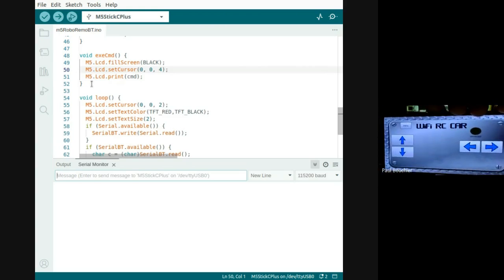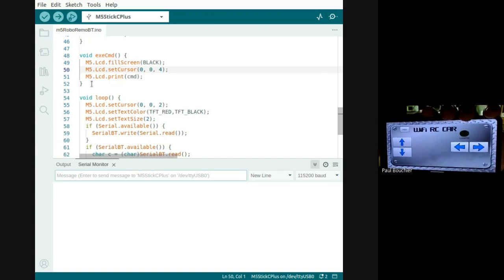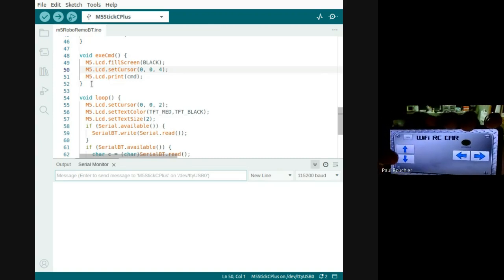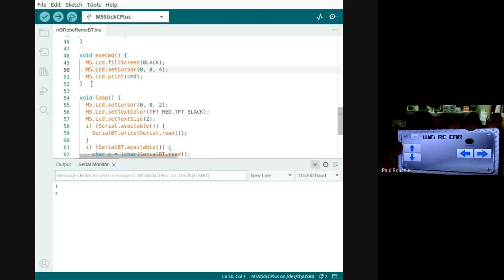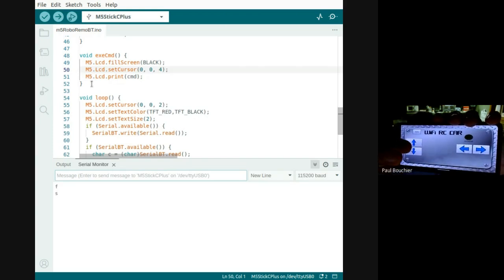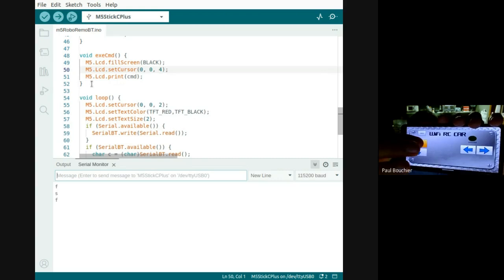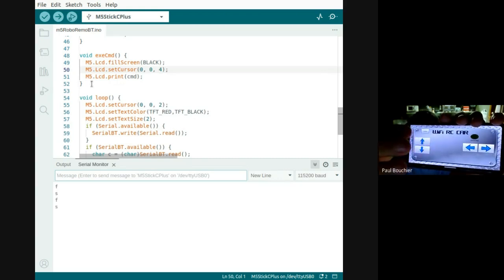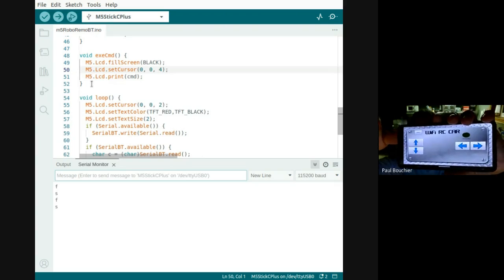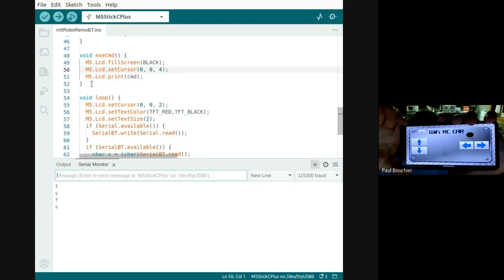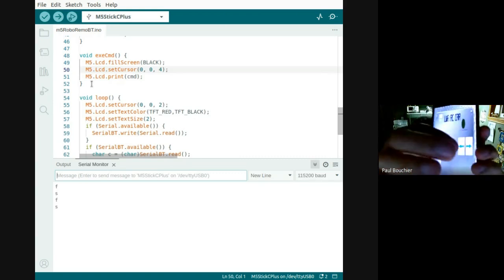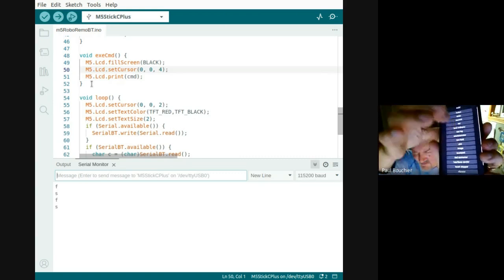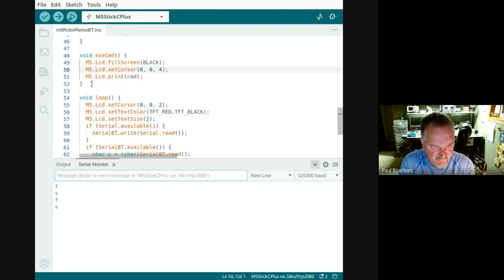And if I press one of these buttons, you should see the output on the serial monitor. So it's F and S. So when that's forward and then stop. So if I press the button, while I'm pressing, it sends an F, and then when I release, it sends an S for stop. So that's just how they've programmed the button, but there's options in the button programming. If I go to editing this UI and press one of these buttons, then that wasn't what I wanted.